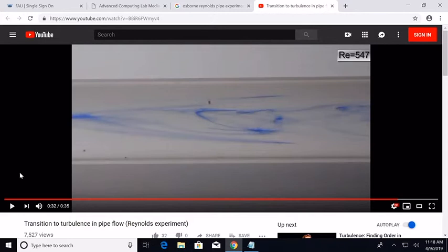Any paint or any solvent, any organic fluid, yes. Exactly. So when you make paint, you want all the pigments to mix together nicely, but they're very viscous, so you have to do it at a high velocity. Otherwise, they will not mix, as you saw. And I will pull up another video where you see it's actually reversible if the Reynolds number is very small. So paint was one example, and in the chemical industry, this is a very important problem.